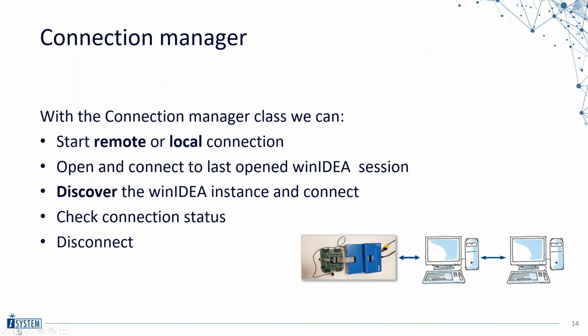This connection manager manages our connection to winIDEA. First, we can start over the Ethernet, as mentioned, but we always need to connect to a certain winIDEA project that is installed inside, let's say, the target PC. Here we can connect over USB or Ethernet to our debugger, and all the settings describing how the connection to the actual target works are there inside winIDEA.